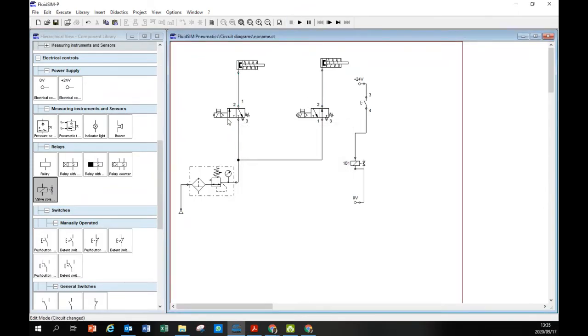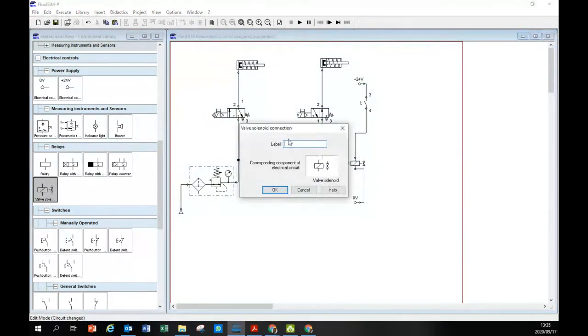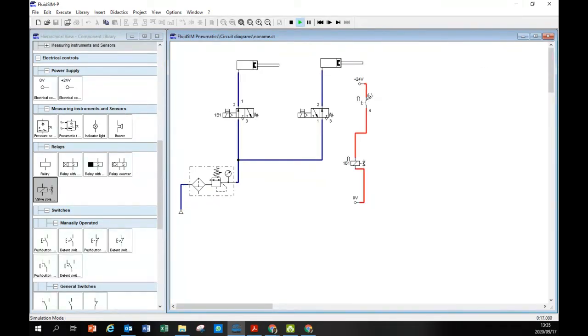I'm going to swap the two. I'm going to put this one there. I don't want to program this. So 1B1. Now we are assigning it. Observe. Because this one is normally open, the air will pass in. This one is normally closed. You see? Normally closed. The air doesn't go through. And when I press here, the air goes through. We've opened the tap. Water's coming out. The tap is called a tap valve.